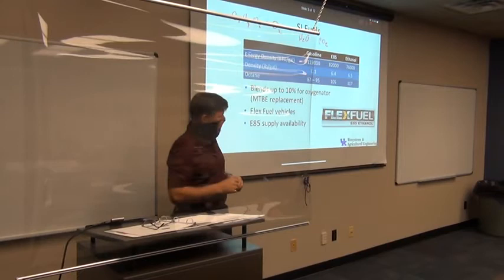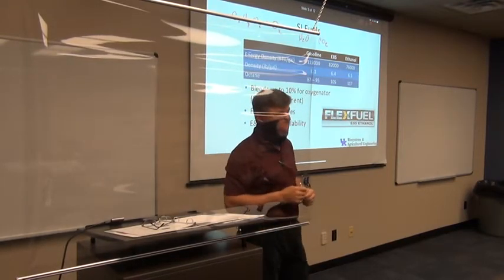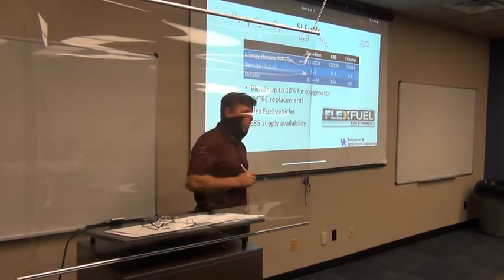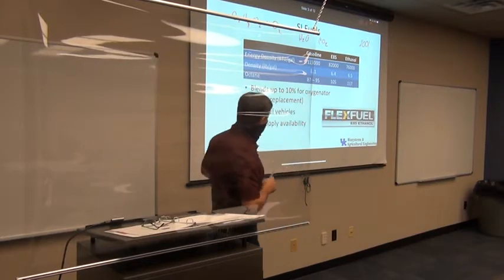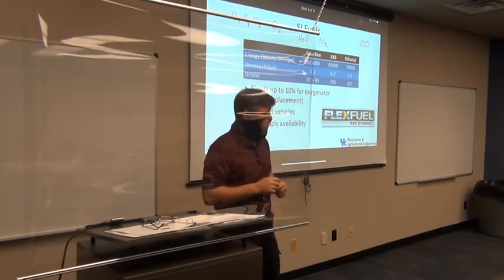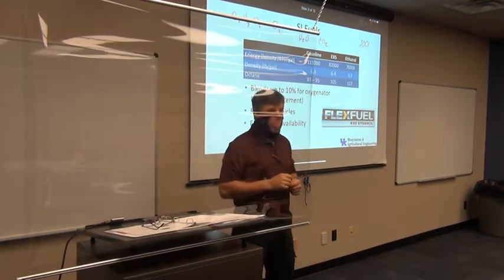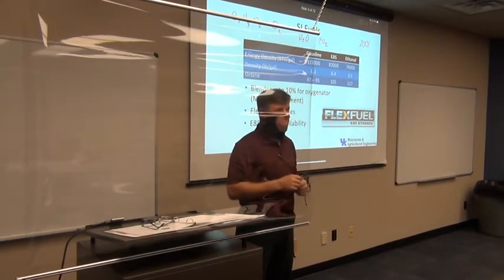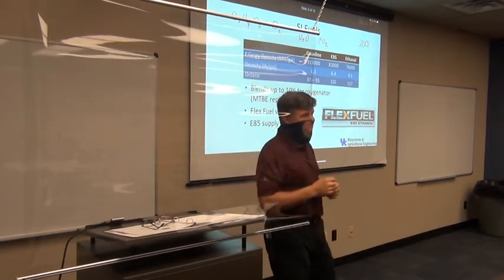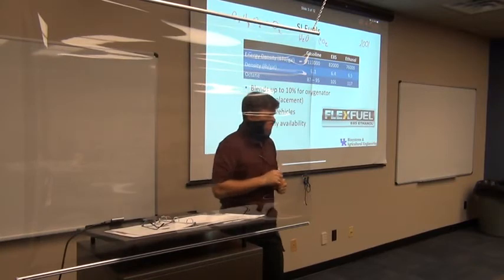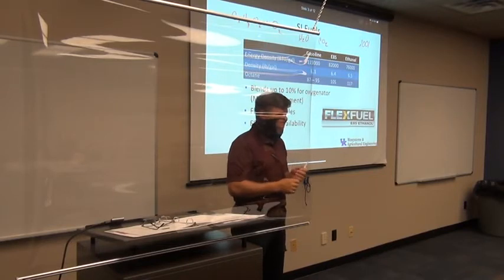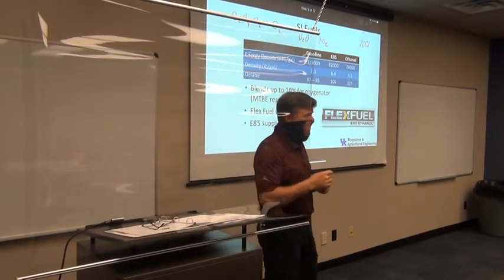A lot of vehicles we buy now are flex fuel vehicles, so you can put pretty much any fuel in it. And actually, any vehicle manufactured after the year 2001 has got to be able to handle up to 20% ethanol in the fuel. So any vehicle that's 2001 model year or newer, I can put 20% in it, and it should operate just fine. Okay. Now, there's a lot of places where we don't want the ethanol in the fuel. Right? Any of you got grandparents who say, I don't want that alcohol in my fuel? You just get some people to talk about that.